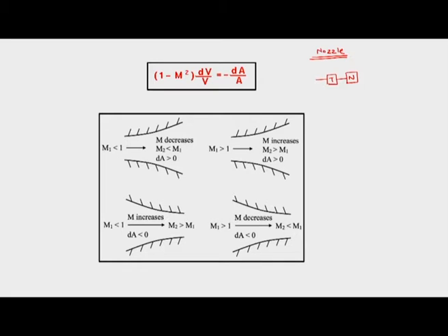But in case of a nozzle, at the expense of enthalpy drop, we have a decrease in pressure and an increase in velocity. So, in a nozzle, pressure decreases and velocity increases. This is what happens in a nozzle. So, with the nozzle we have the following expression governing the relation between area and velocity.